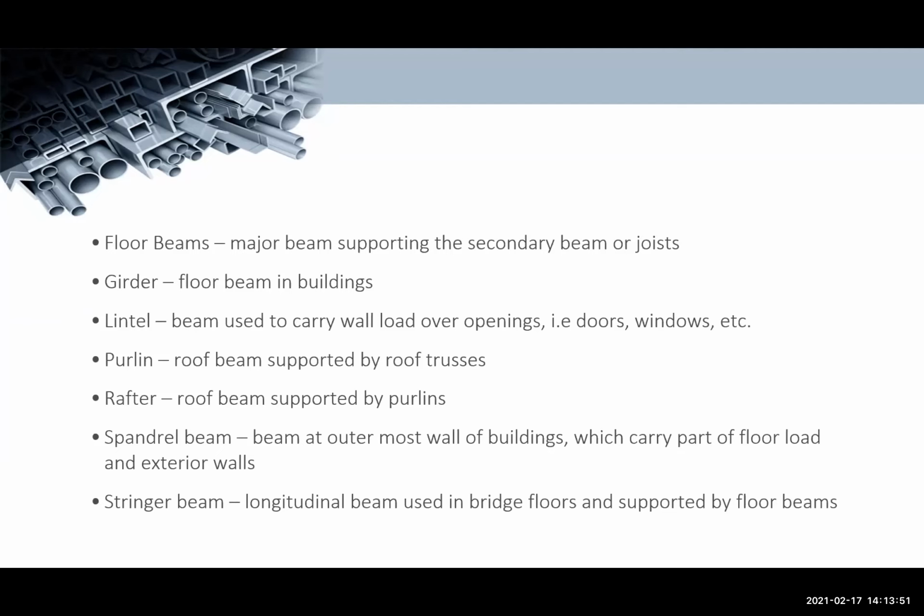Next, we have your purlin. So, yung purlin pala sa roof is a type of beam. So, they are a roof beam supported by your roof trusses. So, I hope you know what a purlin is, no? Diba? Sa truss natin, meron tayong C purlin, most of the time C. Meron tayong CL. So, there are different types of purlin. So, ang analysis ng purlin is sa flexure din.